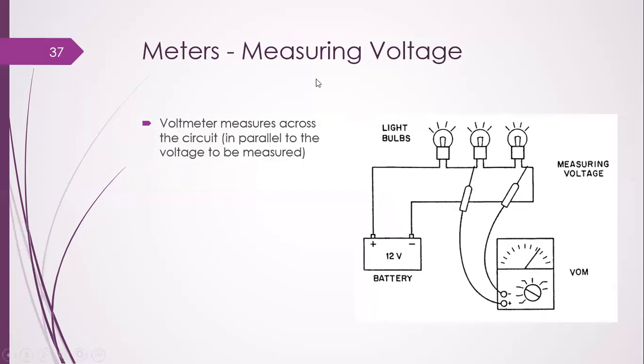Now from the meter, if we need to measure the voltage, then we need to connect the voltmeter by selecting it from the voltmeter selector switch. Then the particular voltage would appear on the analog screen or digital screen of the meter, but we need to connect the meter probes in parallel without disconnecting the cable, either the first one or the last one.